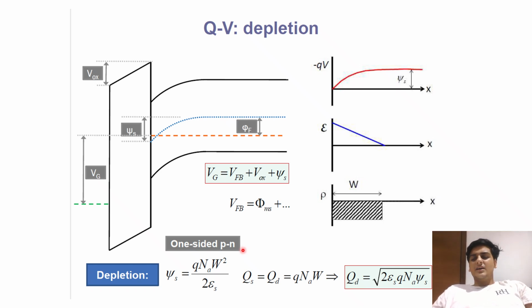I'm sorry if that confuses you a bit, but we just want to invoke the formula that we derived over there. So if you're a bit confused, maybe you can listen to the explanation again or reach out to me. Cool. So this is the formula that we had in the diode, which is that the voltage is related to the width this way. So now we have this relationship between the voltage and the width. Remember, this is the voltage across the depletion region.